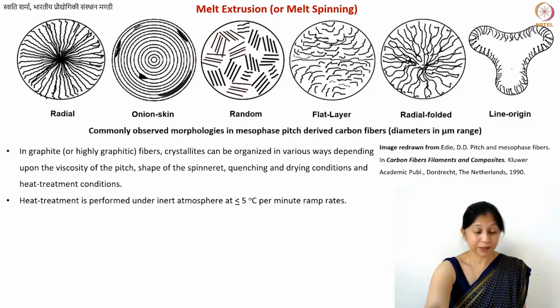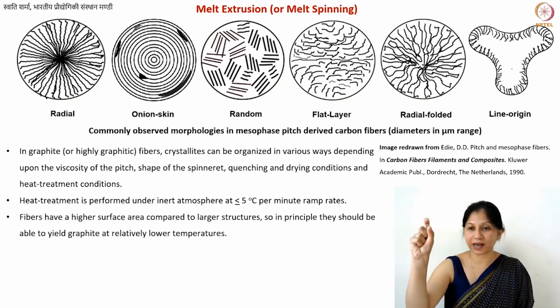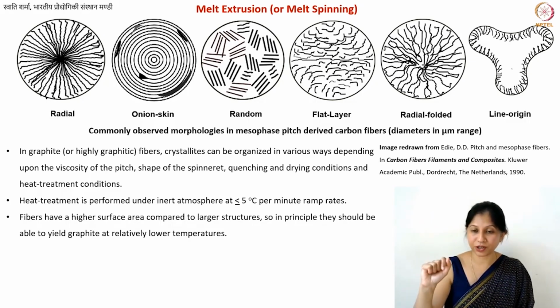Typically the heat treatment is performed in all industrial cases at less than 5 degrees centigrade per minute. That is your temperature ramp rate, meaning how you increase the temperature. Then you keep your material at the final heat treatment temperature for at least an hour. You can also do it for several hours because that also leads to better organization.